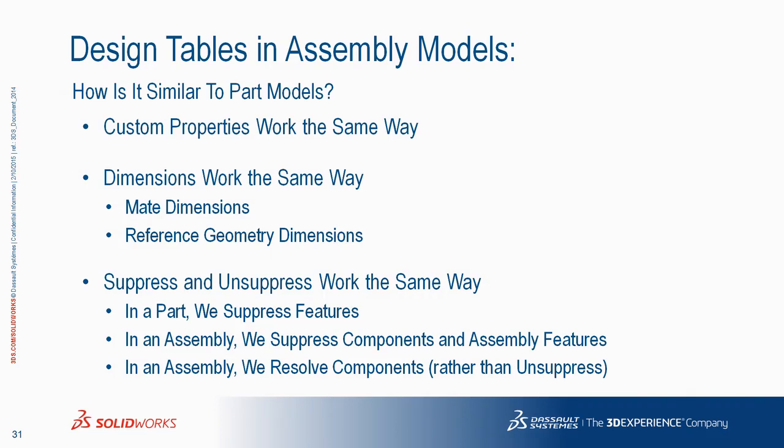In a part, we suppress features. In an assembly, we suppress components and assembly features. And in an assembly, we resolve components rather than unsuppress them. Don't ask me why one's called resolve, one's called unsuppress. I don't know about that one.